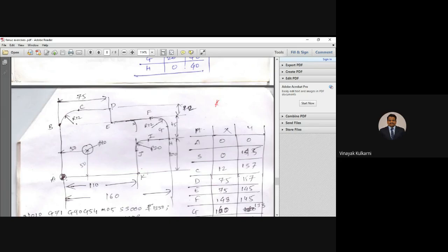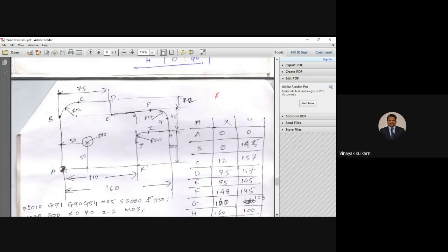Now coming to F, if I draw the coordinate axis like this, y and x, now from this point I am moving downwards. What it will be? It will be imaginary y in negative direction because I am moving downwards. So imaginary y in negative direction means J will be negative. So what will be my point? It is G, this is still in clockwise direction. So it will stand like G02, that is clockwise direction interpolation. G02 X, what is my point H? X160 Y133 at this point.